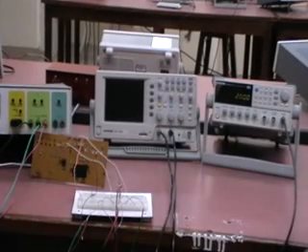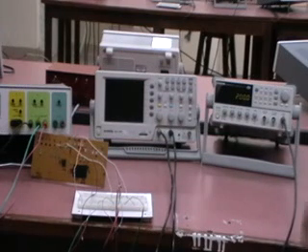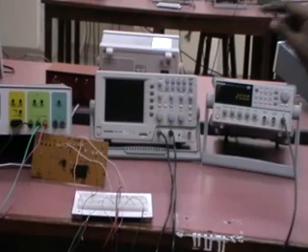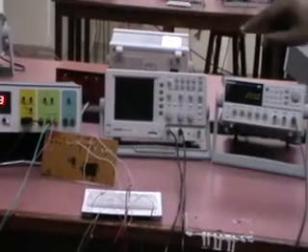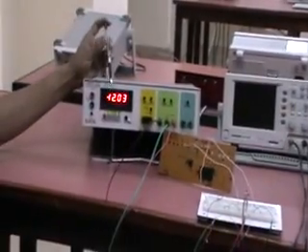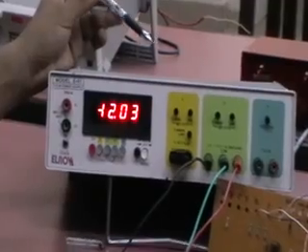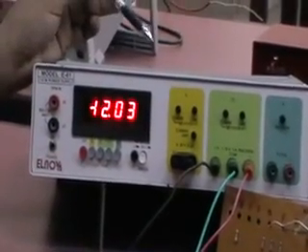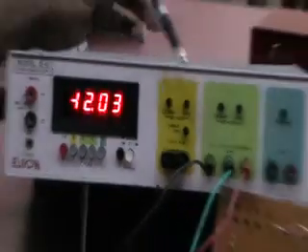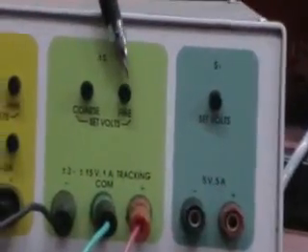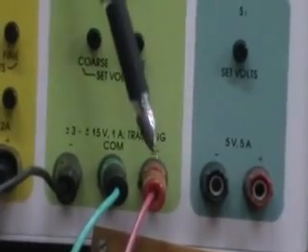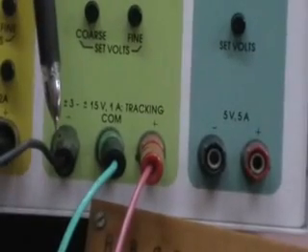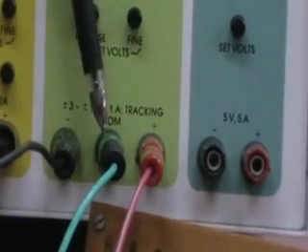Coming to the first part of the experiment, that is observing the IV characteristics of a diode. First, coming to the interconnections, we will give inputs of plus 12 volts and minus 12 volts from the DC power supply. So first switching on the DC power supply and keeping plus 12 volts and minus 12 volts, as you can see in the interconnections, by varying the coarse and fine knobs on the green part. The red wire indicates the plus 12 volts, the black wire indicates the minus 12 volts, and the green wire indicates the common ground.